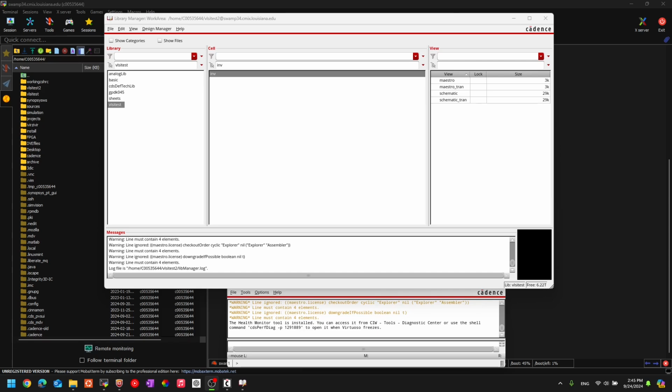Imagine building multiple inverters, and I'm talking about hundreds, maybe thousands of inverters connected to each other, which is really most of the chips today have lots of inverters based on their application. So just putting in MOSFETs and connecting multiple inverters with these MOSFETs might get hectic and might be a hassle for people to read the circuit or the schematic itself.